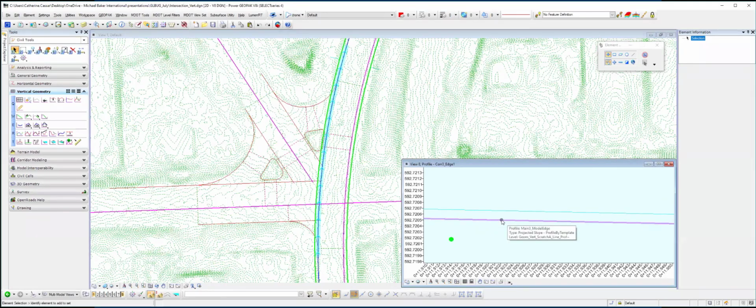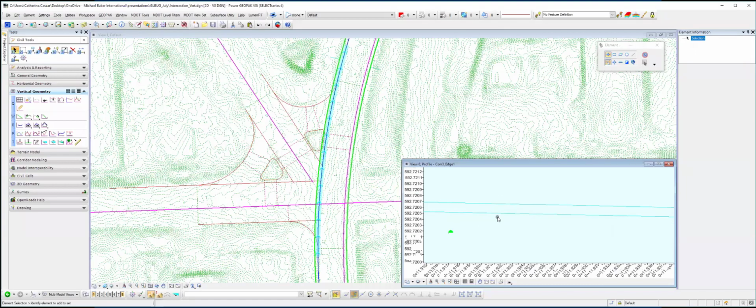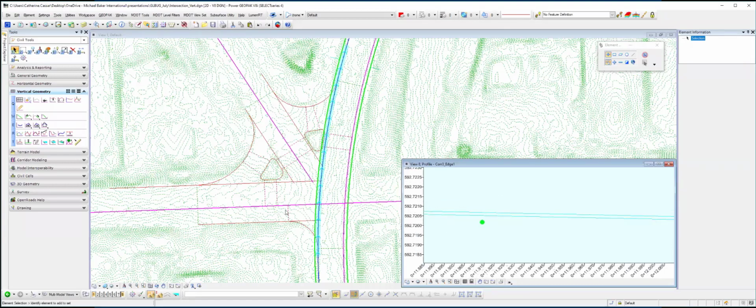This is the modeled edge. This is me reading this blue line directly and putting it as a profile. And the third is me taking it and going profile slope from element at a 2% slope from this mainline edge. And you'll notice what we run into here is I have 3 different locations. That makes it really hard to make sure your models are going to tie down. That's one of those challenges that you have to pay attention to.